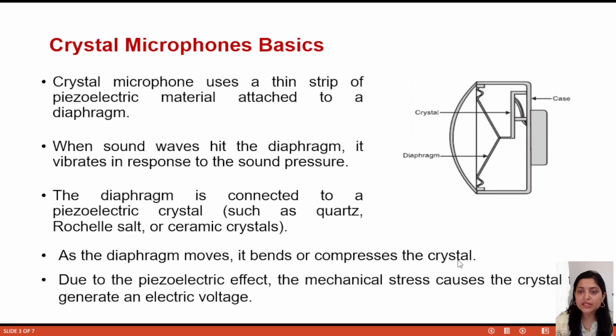The diaphragm is connected to the piezoelectric crystal, such as quartz, Rochelle salt, or ceramic crystal. When the diaphragm moves, it bends or compresses the crystal. First of all, sound wave comes, the diaphragm vibrates, and the crystal connected with the diaphragm receives some pressure too.